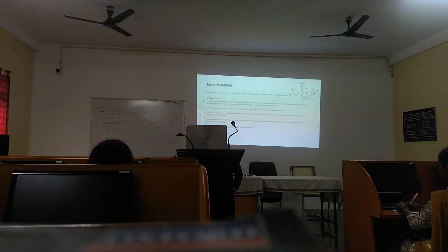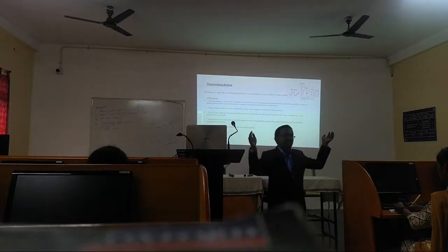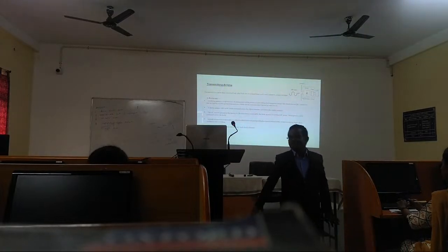Okay. Schottky diodes are usually used because they have the lowest voltage drop, that is, highest efficiency. And cost-wise also they are less costly. Why is it less? Because the losses due to switching or conduction are very low. Large rectennas consist of an array of many such dipole elements, as we already discussed. So how do we construct a large rectenna? By connecting multiple dipole antennas.